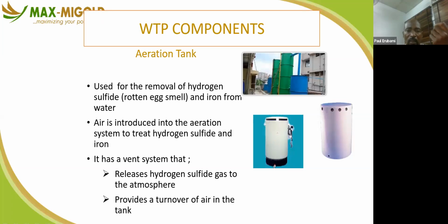So what are the water treatment components? You talk about the aeration tank. We spoke about that one. It is used for removal of hydrogen sulfide and iron from water. It is majorly used to remove odor in water. Here is introduced the aeration system to treat hydrogen sulfide and what? Iron. It has a vent system that releases hydrogen sulfide gas to the atmosphere, and provides turnover of air in